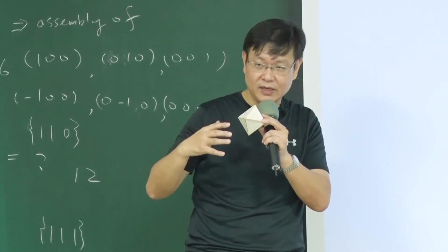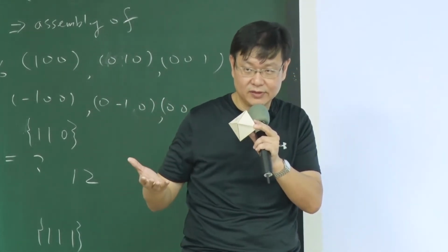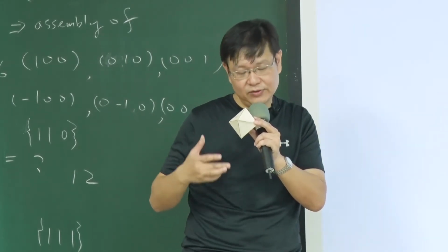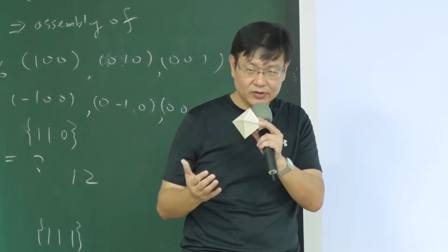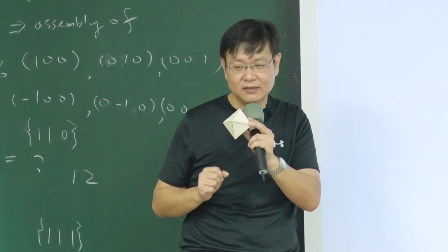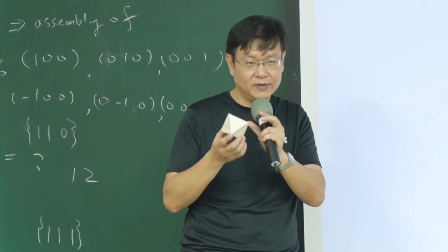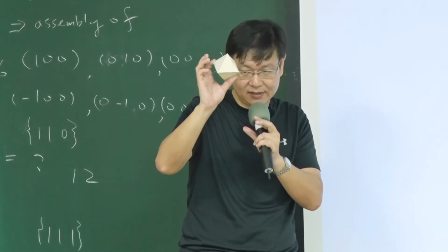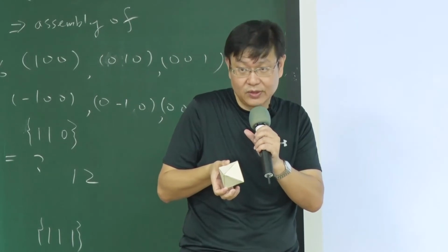During the etching, they may not fall into the final structure. They will have some intermediate structure. So we will talk about that later. They will be more complex. Sometimes we need to use a simulation tool to solve the structure. But for some simple structures, we can have a very rough idea. I give you a very rough idea. But the important thing is the final structure, because no matter how long you do the etching, the final structure will be exactly like this, depending on the direction you look into. Okay?